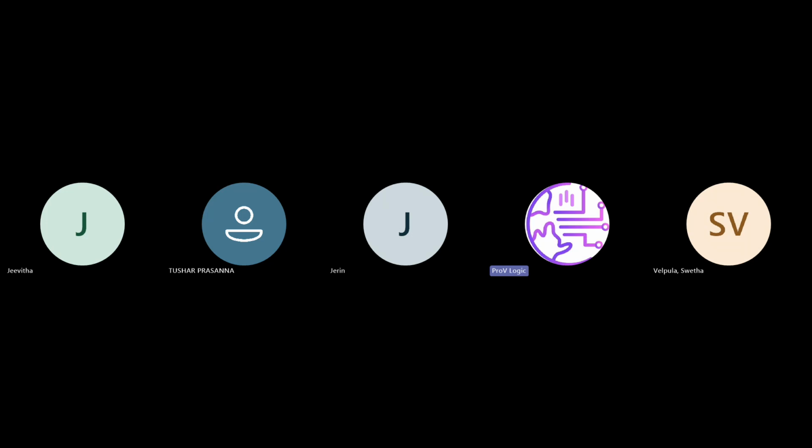Next question. Is the for loop synthesizable in Verilog HDL? Or else how can we do it? It is not synthesizable. We can make it synthesizable by using a generate statement, a generate condition with the for loop. Okay, fine.